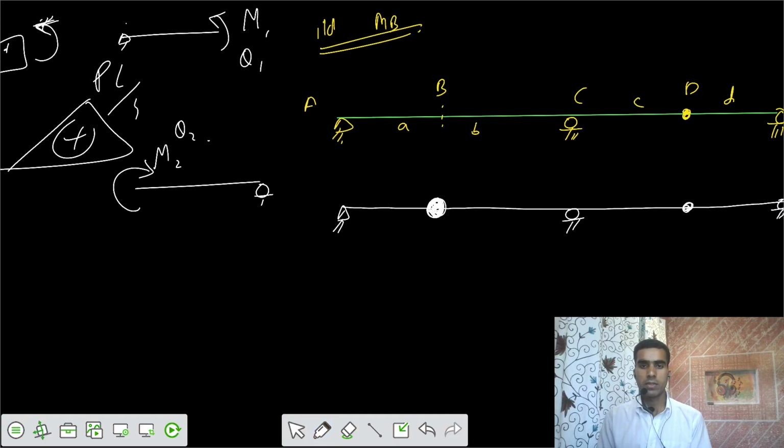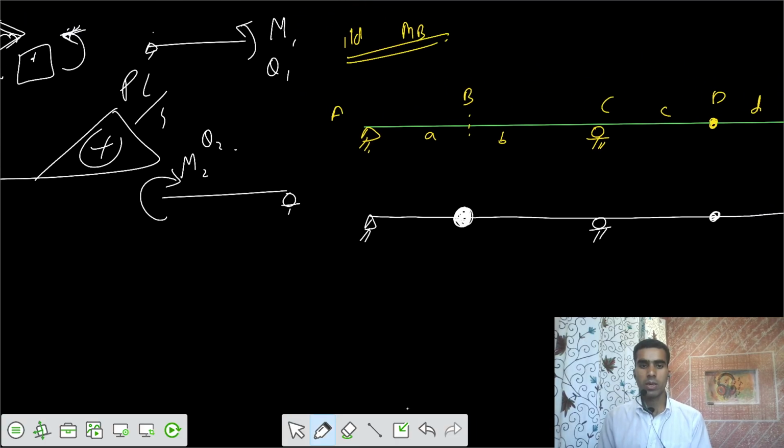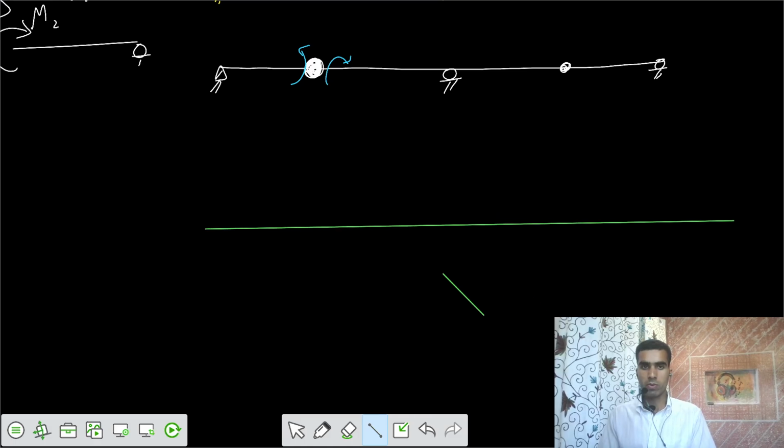So we have to rotate it in this fashion. For the first part, you have to rotate upwards, and in this one, you have to rotate in this fashion. So once you rotate this, you have this internal hinge. You rotate this part upwards, and you also rotate this part clockwise with respect to this, so it would go in this fashion, and you would receive this profile. I would say the profile format would be in this fashion. Up to this part, we have to ensure that other supports are intact.